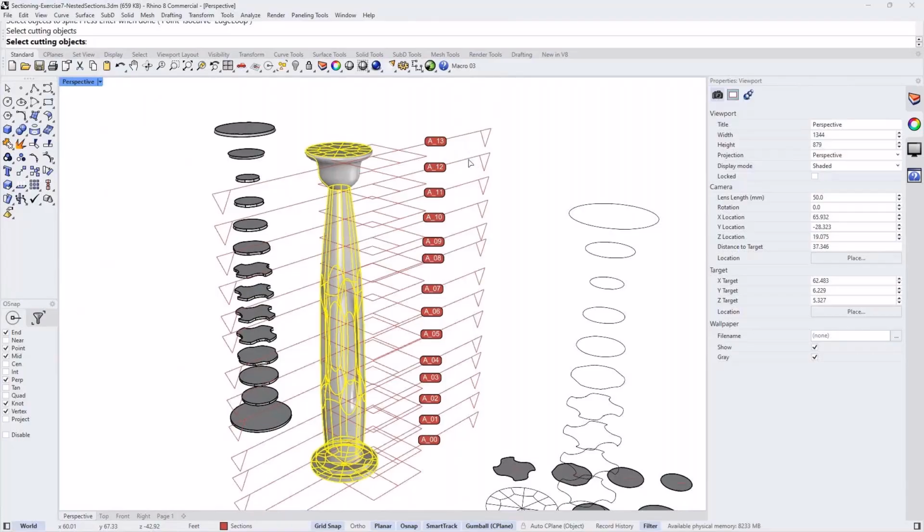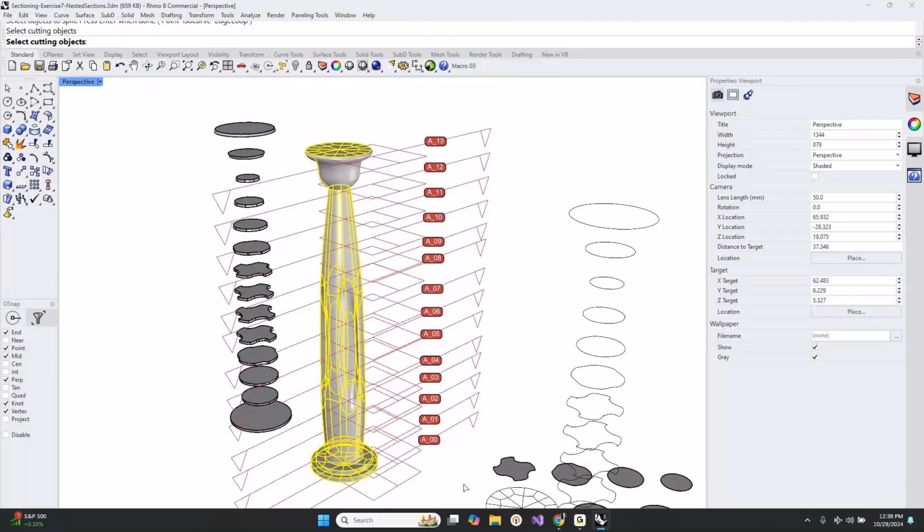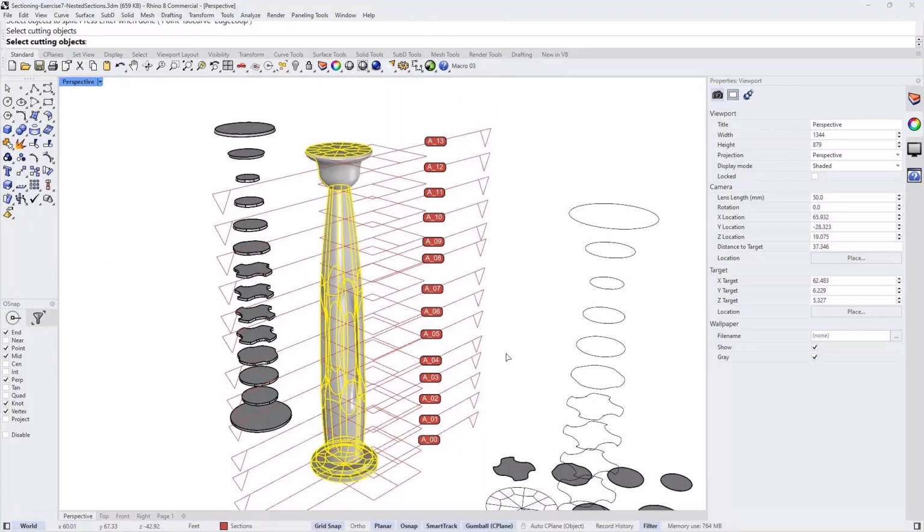It treats the clipping plane as a center plane through your slice, and then you have to give it a specific thickness. But in this case you have variable thickness, as you can see. But a very simple script, even a Grasshopper script, can do exactly what you're saying. You select your clipping planes and then you slice the model with it.